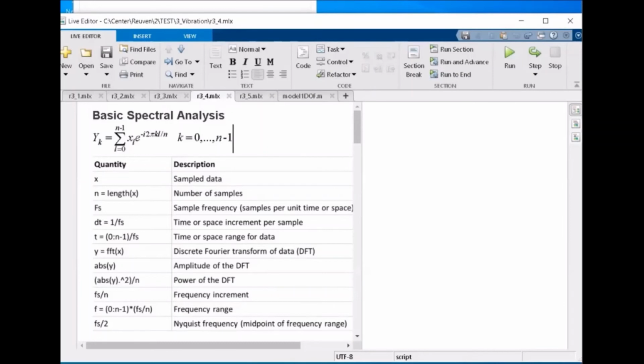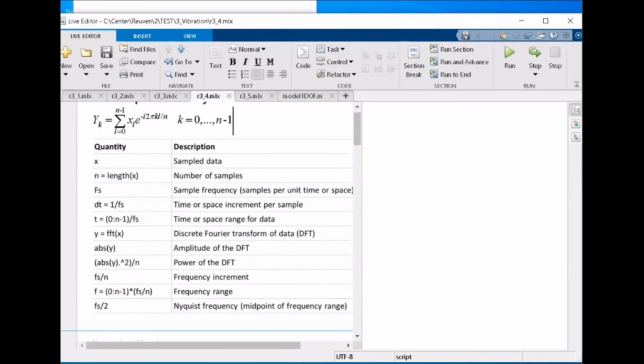The Fourier transform performs a dot product between the real signal and various frequencies of our sine. You can see here we play with k as a function from 0 to n, and k is just the frequency of our exponent, of our harmonic.